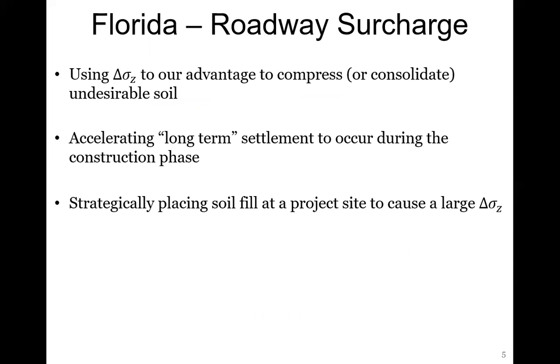So Florida surcharges are kind of unique because it's a workaround where we actually use this delta sigma Z, this increase of stress at a certain layer, to our advantage. We do that to compress or consolidate undesirable soils. We haven't really introduced this term consolidate before, but consolidation basically just means the change in volume due to the dissipation of pore water pressure.